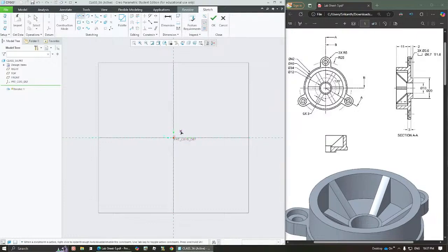Right, so let me start over here. While creating this cross section, one thing you have to make sure of is the equal constraints. You should try to avoid them as far as possible. The way to avoid them is to right click 2 times, and you can see that there is a red cross mark on the constraint of equal to. That means that even though it is getting highlighted, the constraint will not be created. So just go ahead and create.